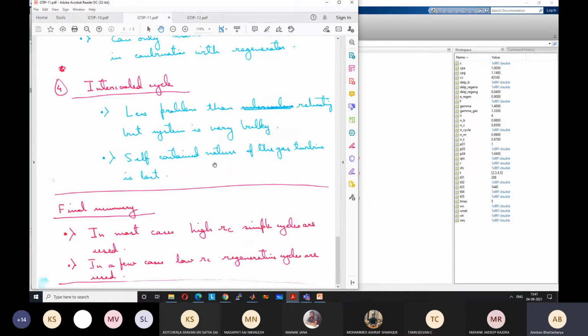So ultimately, what is used nowadays? These things were developed, if you think logically, or if you remember, a long time back actually. Initially, say 80, 90 years ago, the efficiencies of gas turbines, or of turbines, used to be much lower. Larger frictional losses, less pressure ratio, so efficiency was lower, and the maximum temperature that could be obtained was lower. That actually limited the efficiency because turbine blade material was not good. So ultimately, other ways needed to be used to increase the efficiency.